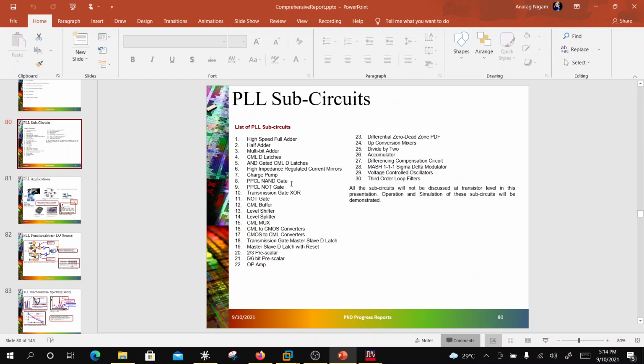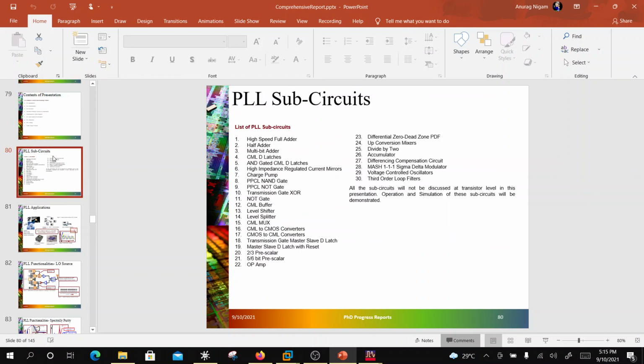Various sub-circuits are in here, and we are going to design all the sub-circuits. We are going to lay them out in a process, and then we are going to integrate this to have an entire PLL, right? Fractional N multi-modulus PLL. Then later I'm going to show you a low power variant of the same PLL using all digital blocks, an all digital PLL we are going to do. So this series is going to cover a lot of things on clocking, and if energy permits, I will also discuss clock recovery circuits in various systems, right?